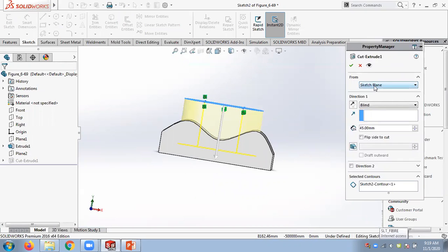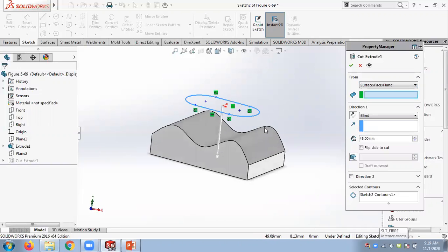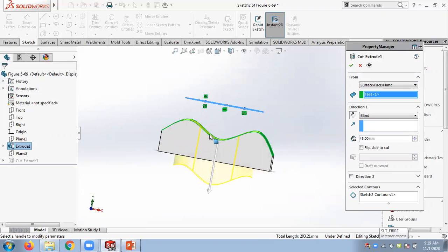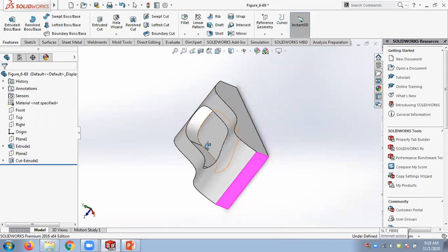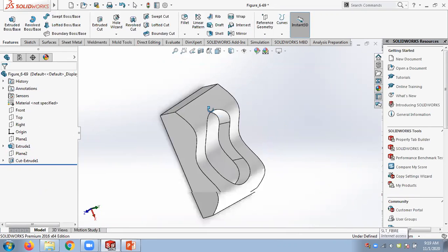So if you want, you can change the way the cutting happens. Now, if you want, you can use this surface place plane tool and start this as the starting plane. So cutting starts from there. But you can see at the end, the end face is taking this same shape. So if you just reduce the value here, like this, end face is also a curve, not a flat surface. So you can see how it works. End face is also a curve. So that may be a weakness.